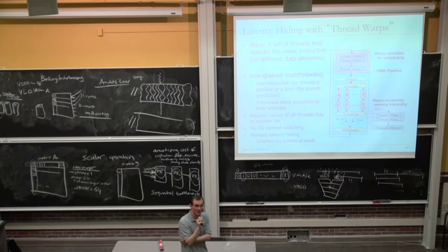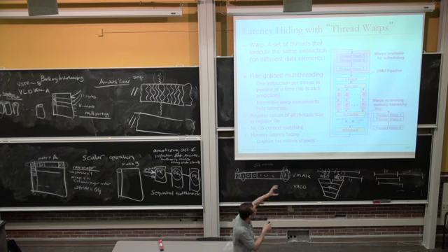So that's a very good question also. It's lockstep within the warp, but again, because these are threads, what you could do is, once you figure out which thread warps are stalled, you could have hardware that analyzes these and tries to regroup warps. You could put those things that are stalled together, and you could take out the thread.